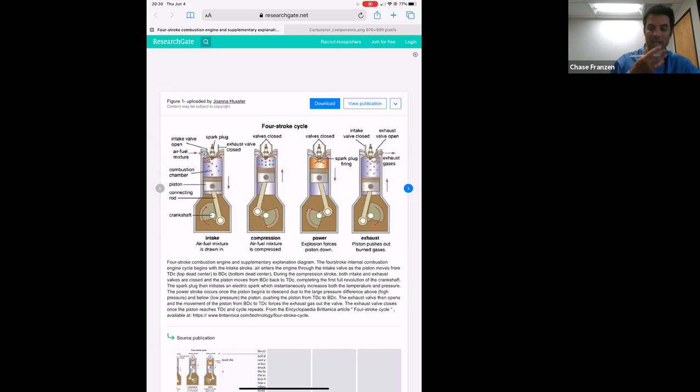So in your car, a lot of times we talk about pinging, this pinging notion. If your BMW takes 92 octane and you put in 87 octane, the idea of detonation is that you don't have this really clear, complete burn in the cylinder. Pre-ignition is when you've got a hot area inside of the cylinder, and the cylinder explodes under pressure prior to the spark plug firing. So pre-ignition, just like it says, is causing the power stroke to happen before it's ready.